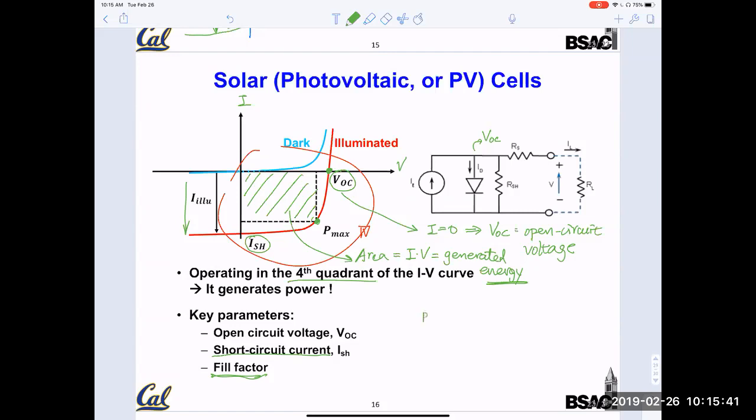And typically, if you buy a solar cell, you typically get something like a 20% efficiency. Depends who you buy it from, the quality of it. But there's a theoretical limit as well. If you get the very best silicon solar cell, the efficiency will be 31% for silicon photovoltaic cell, PV photovoltaic cell, right? And you probably hear TV commercials. SunPower is the one that utilizes single crystalline silicon PV cells, and they are delivering efficiency around 25%. Why not 31%? Well, it's really hard to reach 31%. So it's typically 20 to 25%.